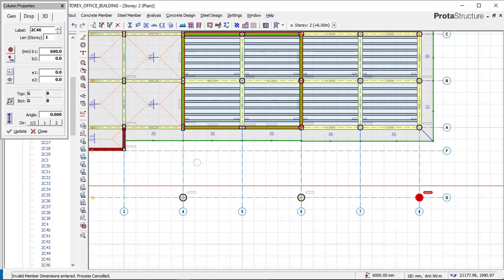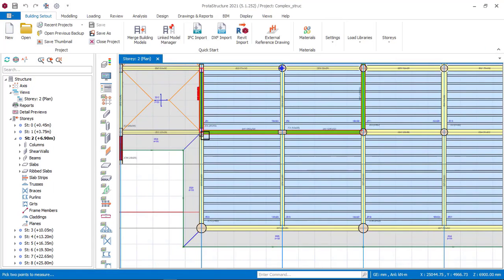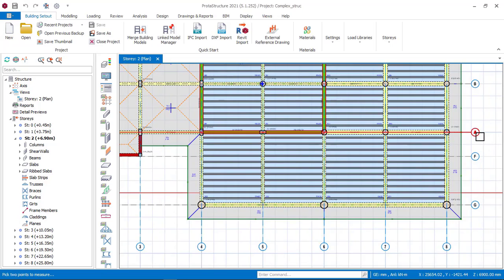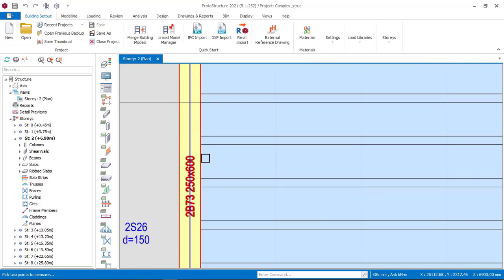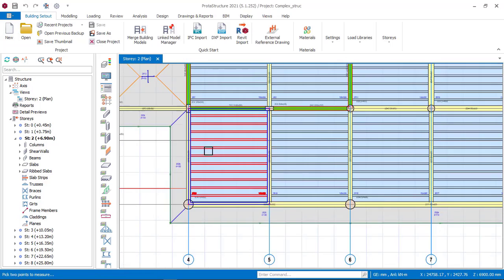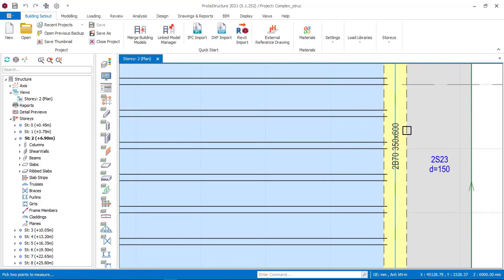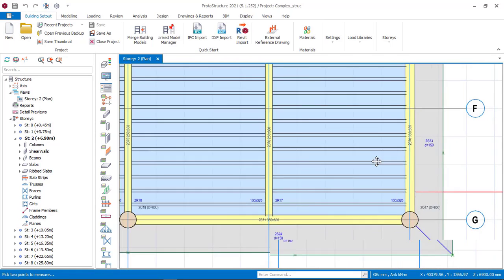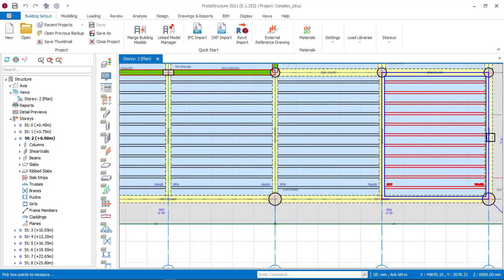Okay, so now let us move on to check what we have again. We also have a beam connecting from this point to this, from grid line A to grid line G. So we have a beam connecting this column to this column, and here to here, and here to here first. Let us take that beam size as 250 by 600. So let us now input those parameters. The same thing happens. This one now is 350 by 600. You can see it here. So only this one is 250 by 600, this is the same thing. Only the last one has different values.